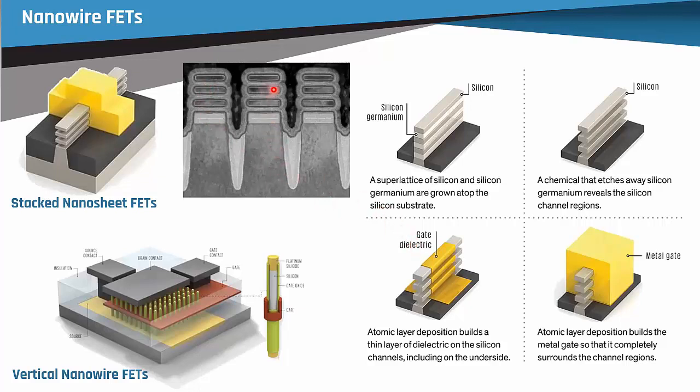And here it's what you call a gate all-around transistor. So if in the FinFET we had 3 sides, the 2 walls and the top as the gate, which made the electric fields, now we have it from the bottom as well. So really each of these wires is completely surrounded by a gate, and we can really turn off the transistor well, get lower leakage or better Ion to Ioff ratio, and that's what is supposed to drive the next few, and maybe last, I don't know, pure, I would call it CMOS FinFET type of designs.